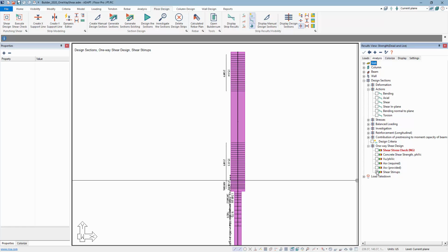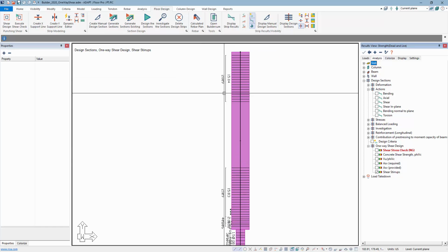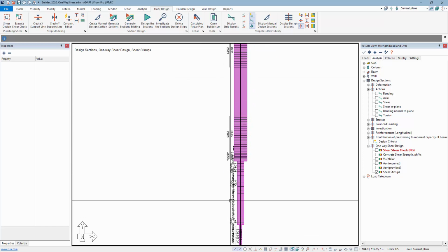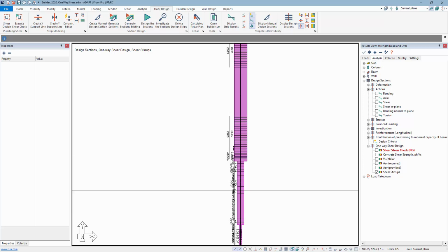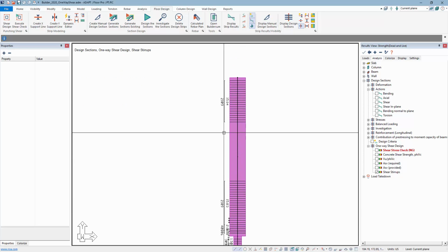And this is laid out, it's flattened. This is obviously a top view of the beam, and you can see the different groupings here for these stirrups. And again, you can modify the text size if there's overlap in the output. And I want to compare this to the previous ways that you were able to get one-way shear reinforcement in this program. Previous ways are still there. This is just a newer, more condensed, efficient way to produce the results.